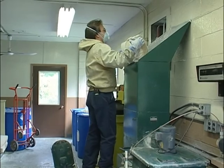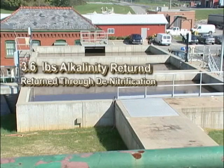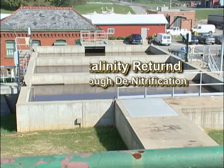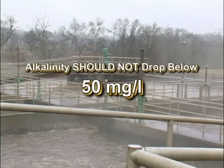It should be noted that for facilities that have an upfront anoxic zone for denitrification, approximately 1/2 of the alkalinity that is consumed for nitrification is returned to the system through denitrification. As a rule of thumb, the alkalinity should not drop below 50 milligrams per liter at any point in the process.